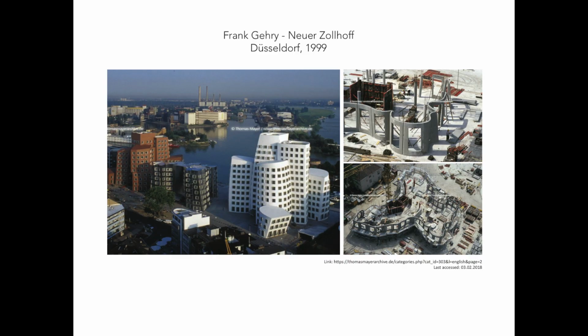The more recent introduction of computer numerically controlled manufacturing processes and new formwork materials have introduced new possibilities for non-standard formwork. Materials such as EPS allow for accurate transfer of double curved surfaces and relief. This building, the Neue Zollhof in Düsseldorf, was the first large scale building to employ this formwork technique. All the individual panels were unique and they were milled